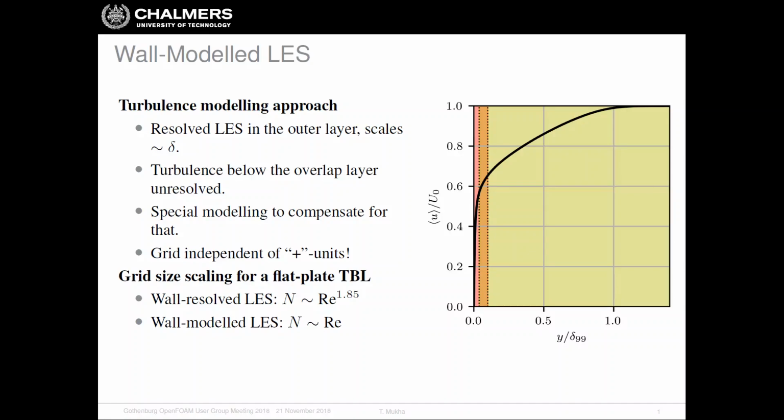Of course, if we go for that kind of approach, then we have to introduce some special modeling to compensate for the fact that we have ignored these important turbulent scales in this pink rectangle here in the inner layer. And that is then the wall modeling.